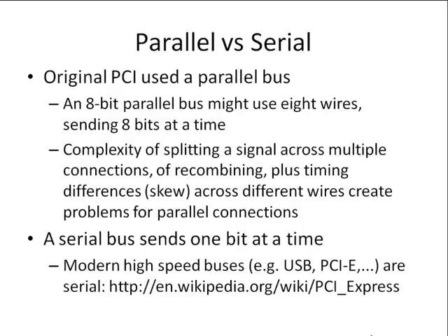But there's some complexity there: the single byte has to be split across multiple connections, and then when it's received at the other end it has to be recombined, and there can be ever so slight timing differences just because of the different lengths of the wires connecting both ends of that parallel bus. Tiny timing differences create a skew across the different wires, and this creates problems for parallel connections. You have to wait till all the bits have arrived before you can do anything, and you have to recombine the different parallel signals into one byte before you can do anything with it.